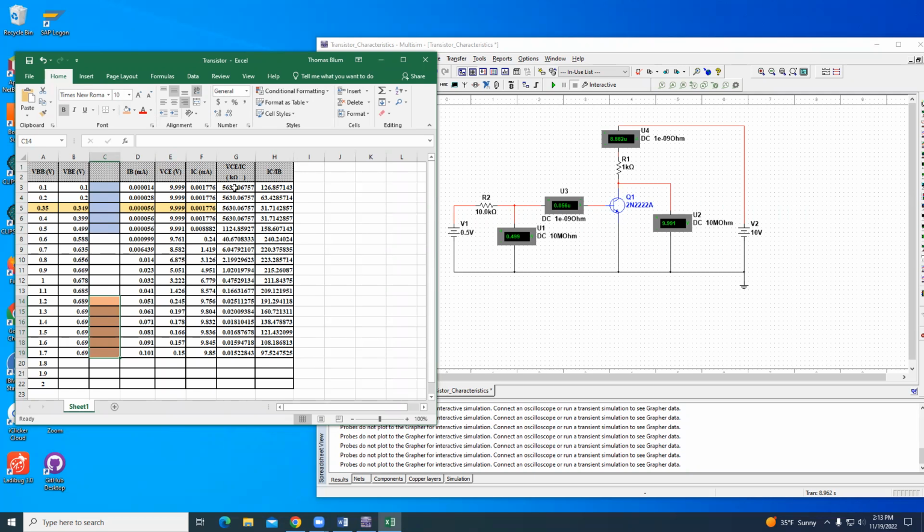I would call this the very high resistance region. This is starting to change at 0.5, but it's still thousands. So we could have cut it off here. I'm not interested in precise cutoffs, but just identifying roughly the three regions. Here's a region where it was sticking at 5,600. Here it's beginning to change, but it's in thousands. So you could decide this off region was 0.1 to 0.4 or 0.1 to 0.5. I don't think that matters too much.